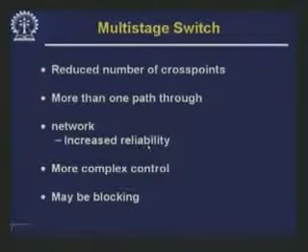It works, but it is not, once again, using a bus etc. You will not get a very fast switch this way, but this works fairly well. If you want to go beyond this, that means you do not want so many lines etc. As I said, even if you have 1,000 subscribers you want to service from the same switch, even if in a knockout switch you have 1,000 buses inside, which is not really feasible technically, we go to the other kind of switches which I showed earlier, namely multi-stage switches.